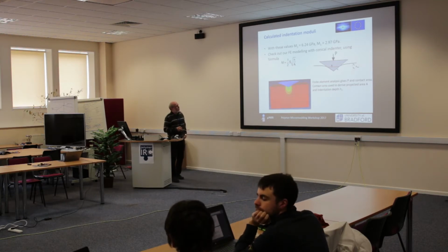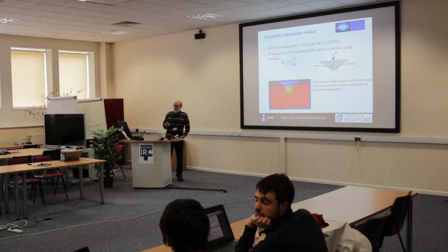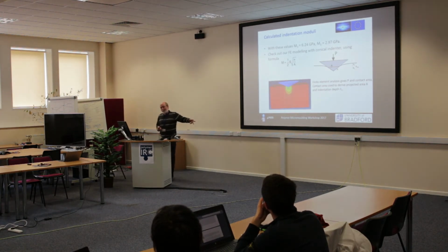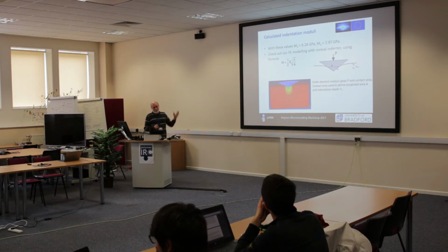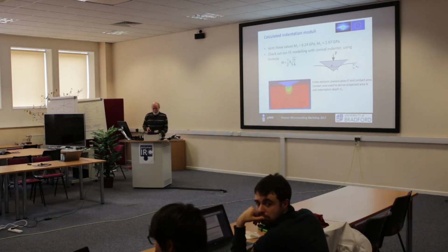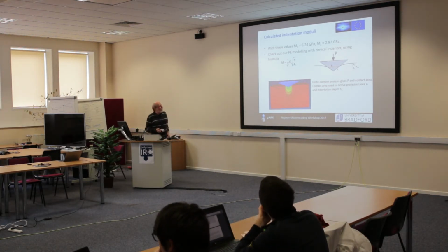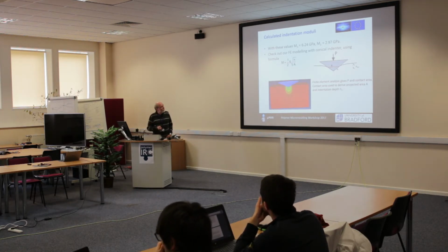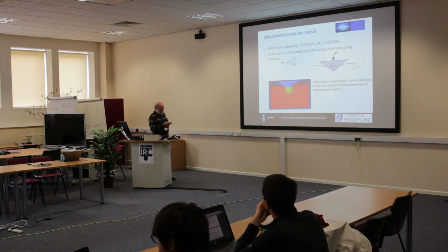And the other thing I'm not doing is including any plasticity in this analysis, because it's just a nuisance. We can include plasticity in the analysis and get realistic looking indentation and unloading curves, but then you've got to just measure the unloading, calculate the unloading curve and ignore the loading curve, so it's much better to not put any plasticity there in the first place. Just straightforward. So the unloading curve and loading curve lie alongside each other. Okay, so we do that.